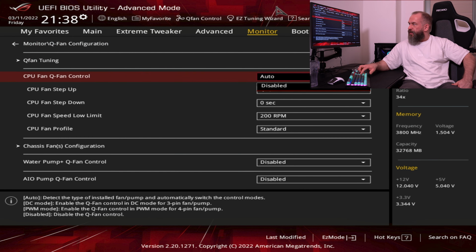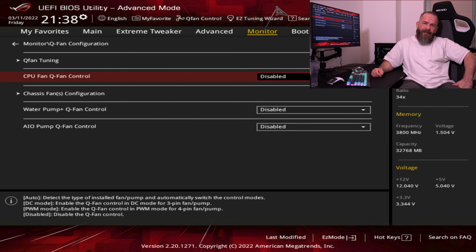First thing we do is set the CPU Q-Fan to disable. Why am I doing this? When I do this and you use the right pins on your motherboard, you let the fans connected there go with the highest spin rate they have. I'm always doing this. You hear this now? It's not loud because those are Noctuas. That's 3 of them pushing the air through the radiator of the CPU, and you can see the temperature will decrease now.